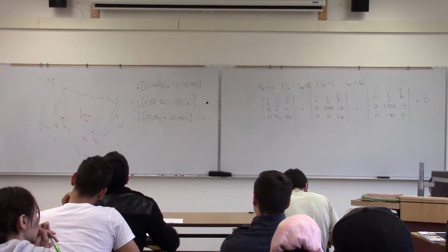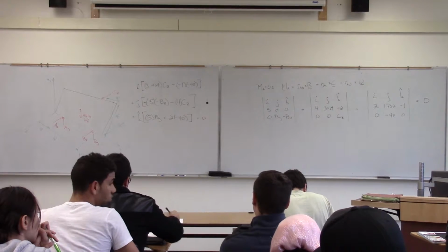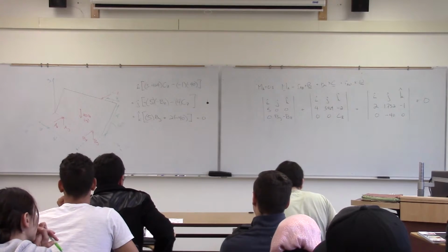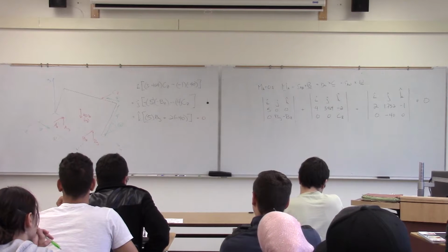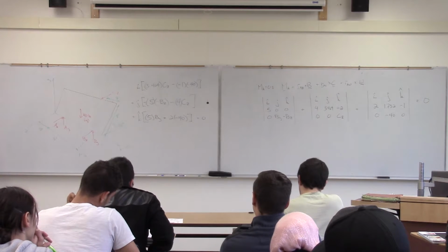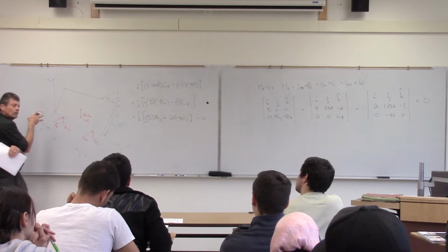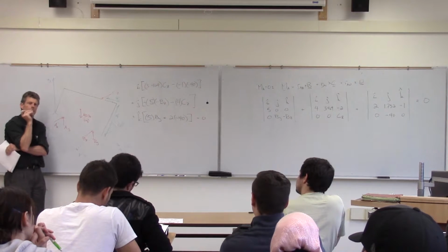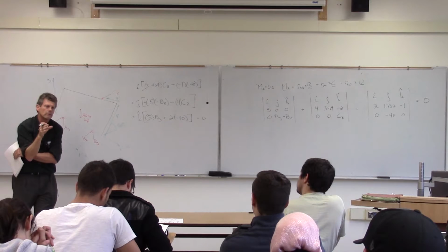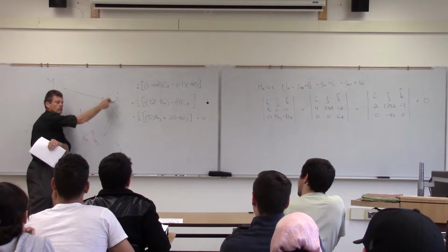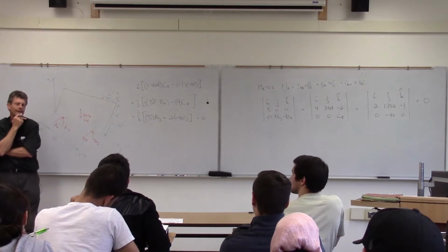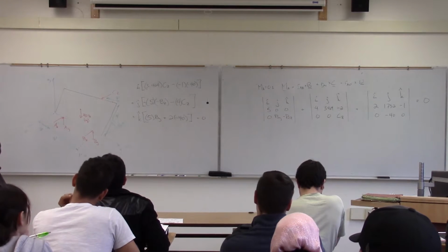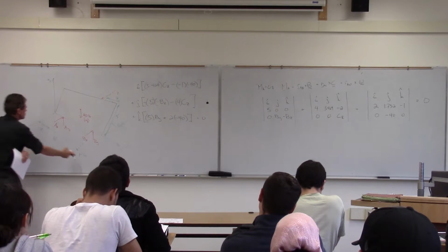Yeah, and then another concern I had was, would AZ and BZ be equal, because the board is leaning on the right side against the pole, so I don't know if those forces would be equal or not. Well, we'll solve that, but think about it. If everything was symmetric, I would agree with you. But the problem is we've got this guy over here, not exactly the same distance from the center of mass. Yeah. One's 2, one's 1. Oh, yeah, that's right. This one's 1 and this is 2.